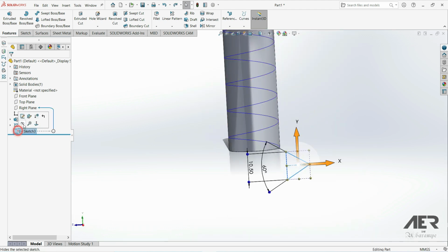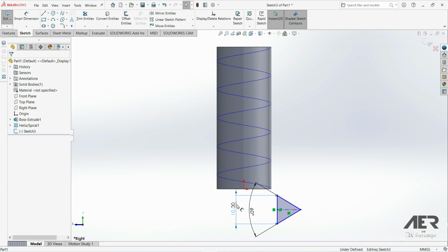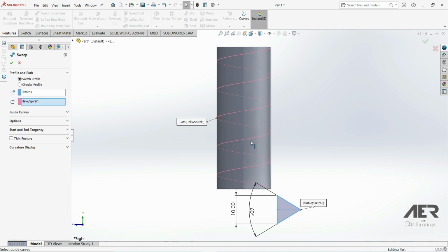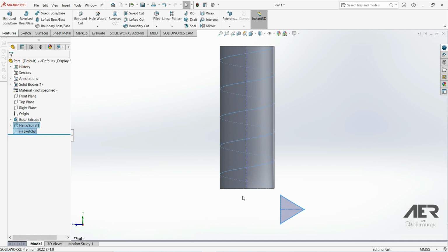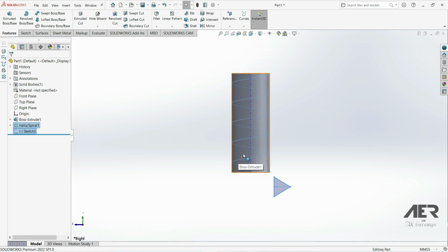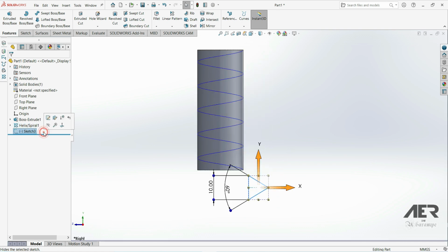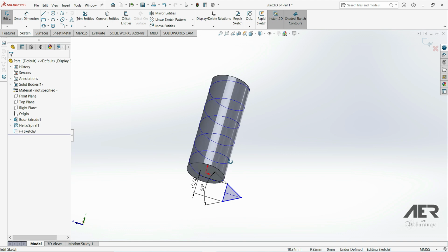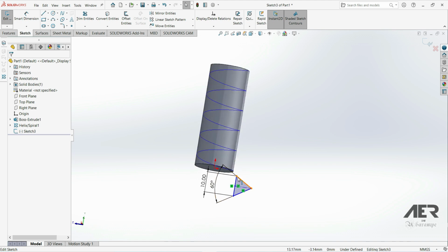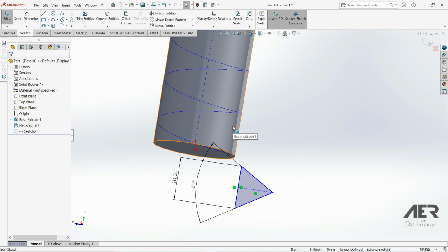In this last sketch example that we should avoid, in my Solidworks version with the length of this triangle, it doesn't work. It just says the sweep operation failed to complete, and that doesn't really tell you anything about what's actually going wrong. This happens because there is most likely a zero thickness error in the sketch. But if you reduce or increase the length of this triangle, then it will work, because we don't have any sharp corners or two points touching each other as they sweep. But I don't recommend that you do this because potentially this can cause problems. It is definitely much better to avoid.